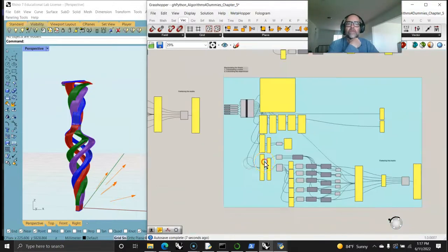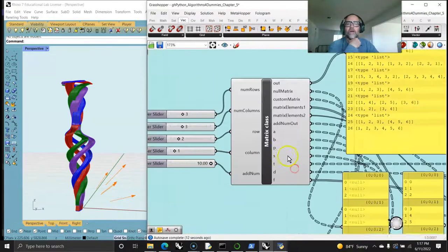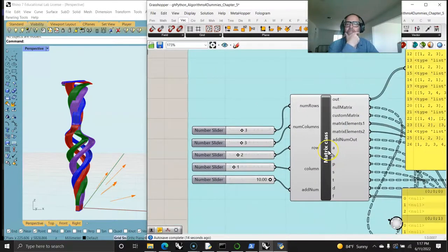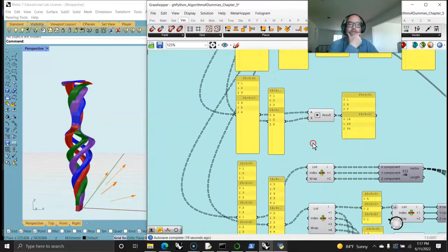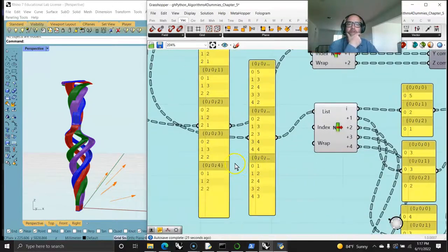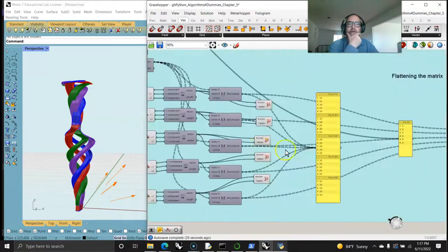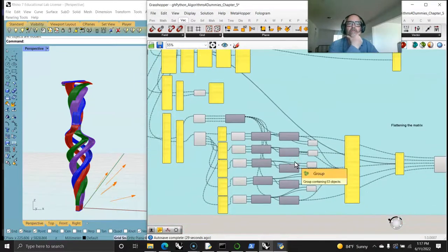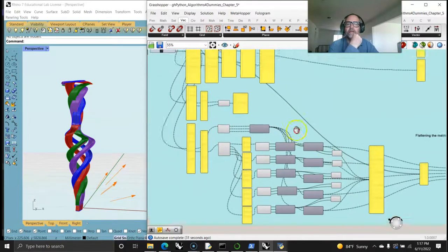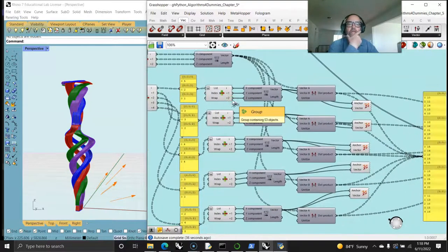You can see that here we start getting into a little more complexity, and we build an entire matrix class in the end that can do an awful lot of things for us, and I'll customize that as well to actually pull out data, pull out different trees, have much more control over it, start playing with different data as well, and show the visibility of what's actually happening in dot product, and break down things like grafting and flattening and simplifying this way through GhPython as opposed to the Grasshopper 1 path mapper and other tools for understanding sets.